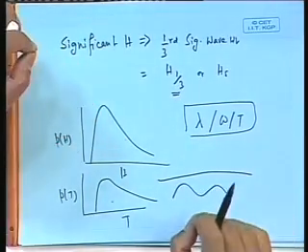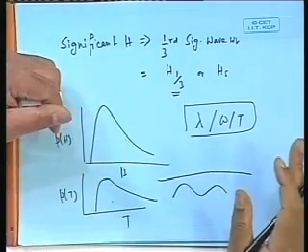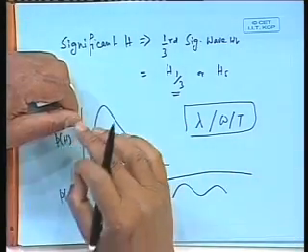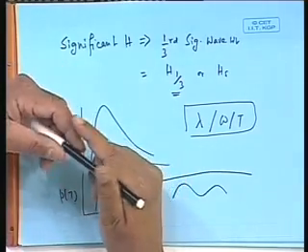If I just take height as a parameter, I don't know what the length is associated, then I do not really get a feel of the ocean. Because I can have, say, 10-meter height, I can say that 10-meter occurred many times, fine, but the wavelength is 1 kilometer. So it looks still like that. Histograms don't give that. Histogram cannot give that other side.